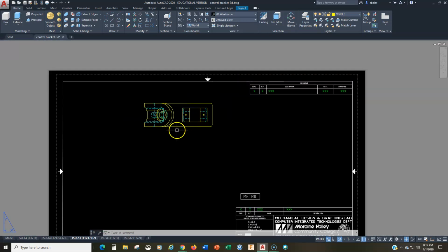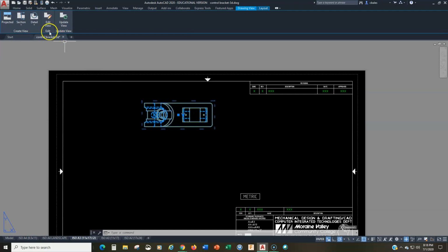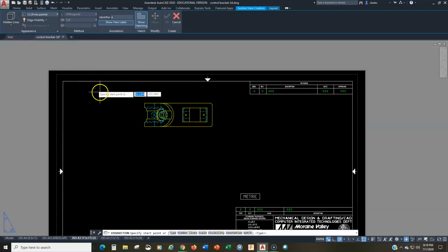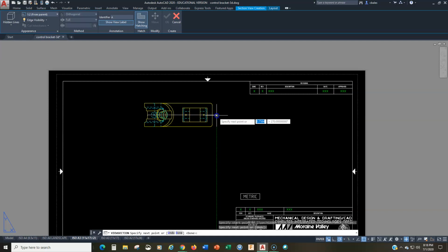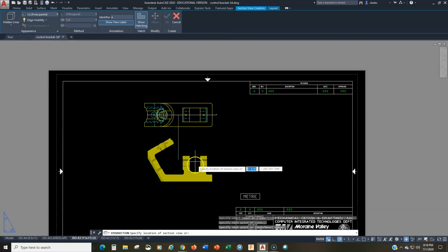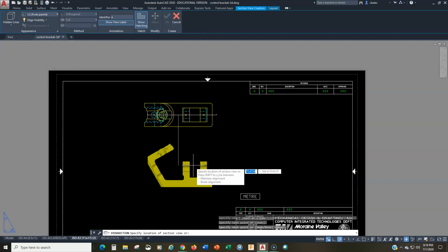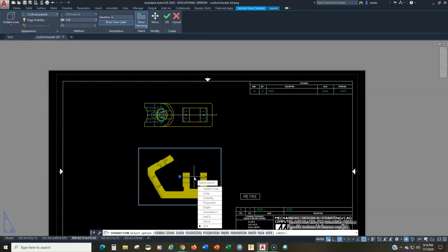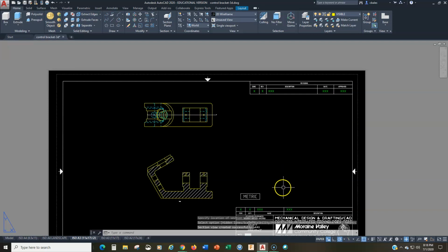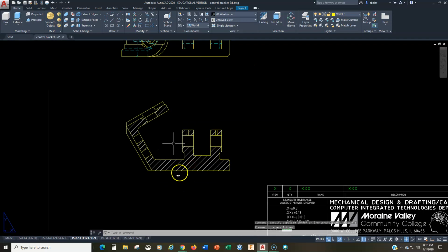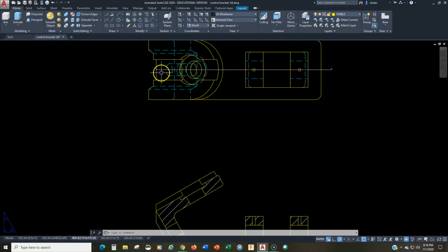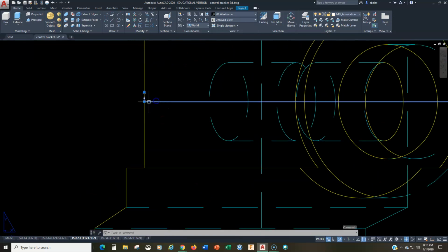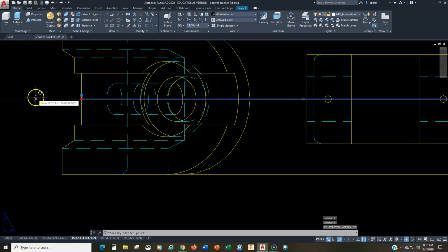All right, so now let's create the section view. So I can click in this and go to section. I want to create a full section, so I'm going to click on that, click here, make sure I'm getting in the middle, hit enter, and drop that down there some distance that looks good. This metric thing is going to get in my way, but I'll delete that. Enter, or pick, enter, and there we go. Now I'm just going to delete this right here. You can see this is truncating it a little bit, so let's adjust this. We'll pull this out a bit right about there.